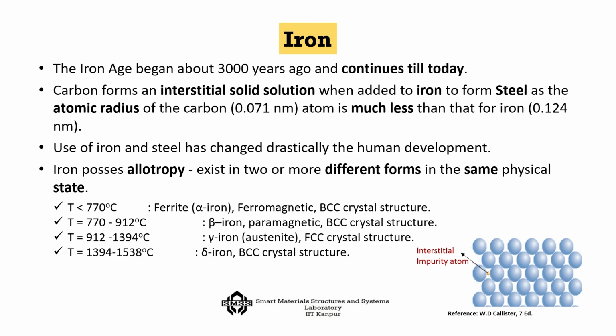Now, carbon mixing with iron, although initially serendipitous, later became almost regular in nature, and that is because people understood that it forms an interstitial solid solution. Okay? That means, imagine that this is an iron atom, this is an iron atom, and this one and this one. The space that is inside them is good enough for smaller atomic radius materials, and carbon, as one material very abundant as an organic material, let us say from wood or charcoal, you always get carbon.